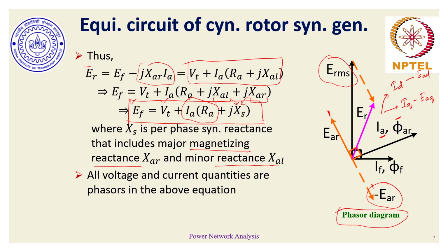And if we remember, in a salient pole machine where the rotor is tapered with salient pole, with north pole let's say being marked here and south pole being marked here, the magnetic axis along which the air gap is minimum in a given salient pole rotor, we call it to be the direct axis component, whereas the quadrature axis component is perpendicular to the corresponding direct axis component.